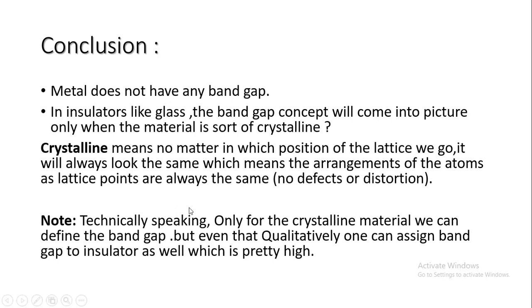Technically speaking, only for crystalline material can we define the band gap, guys. If your material is crystalline, you can define the band gap. But even then, qualitatively one can assign a band gap to an insulator as well. Qualitatively you can assign a number to this kind of insulator, whether it is crystalline or not, but you cannot define the band gap if your material is not crystalline. Qualitatively one can assign a band gap to an insulator, which is pretty high, like 6 electron volts.